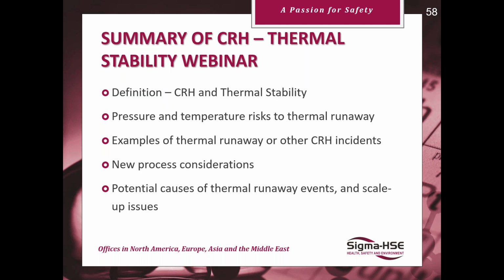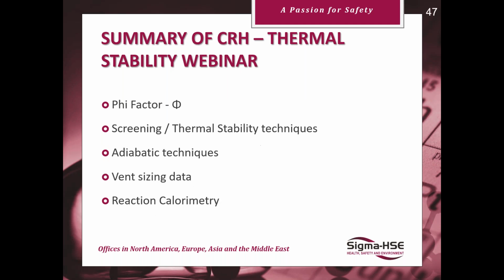We've gone through some examples of worst cases or other CRH incidents, how this links into new process considerations or alterations to a process, and what the potential causes of thermal runaway events and scale-up issues might be. Integral to underpinning all of these, we've got the 5-factor, our screening and thermal stability techniques that we can offer, adiabatic techniques, vent sizing data and how that might apply, and reaction calorimetry.